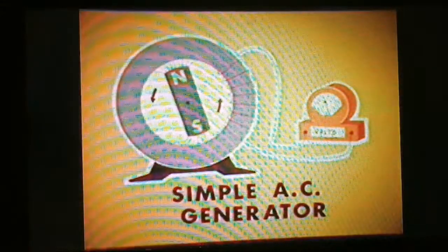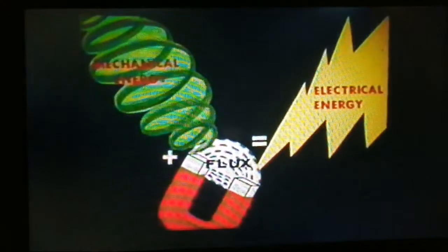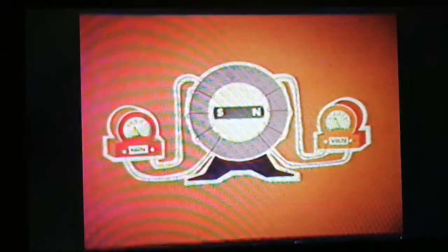Well, let's look at a simple generator. Each time the field of a magnet moves through a coil, voltage is produced. Mechanical energy, motion, plus magnetic flux create electrical energy. The efficiency of this can be increased in several ways. First, by making both poles of the magnet work at the same time.